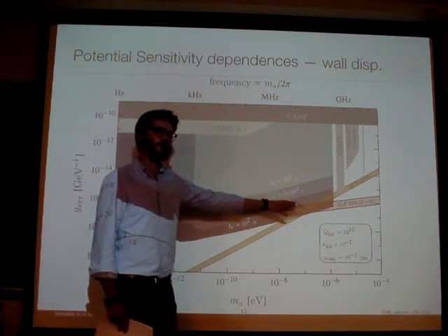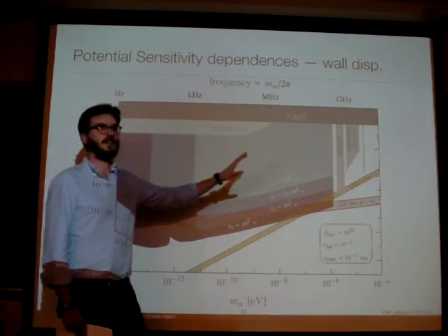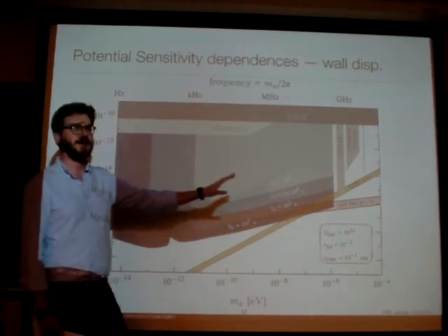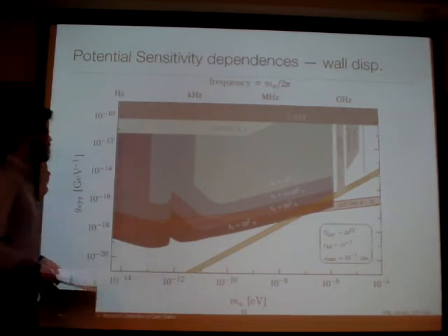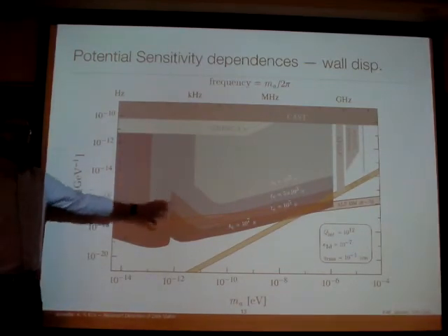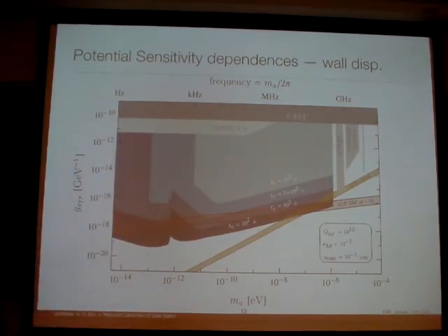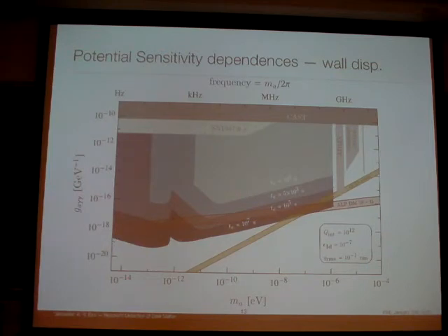Only when you're thermal noise limited can you really give a nice SNR expression, because there it's relatively straightforward. Down here, where there are all sorts of different noise sources which are comparable in size, it's much more complicated.